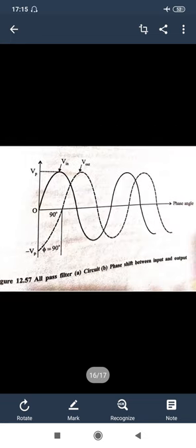In this case I have also denoted the phase changer, with the graph of the phase shift between input and output, where the output lags the input voltage by 90 degrees. I have also explained that the gain V0 by Vin is unity, that is, V0 is equal to Vin throughout the useful frequency range. By the phase angle phi, we calculate the phase shift between V0 and Vin, which is a function of frequency.